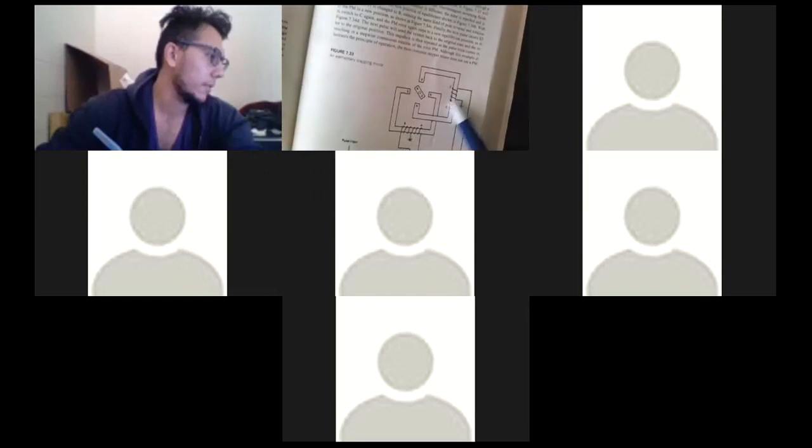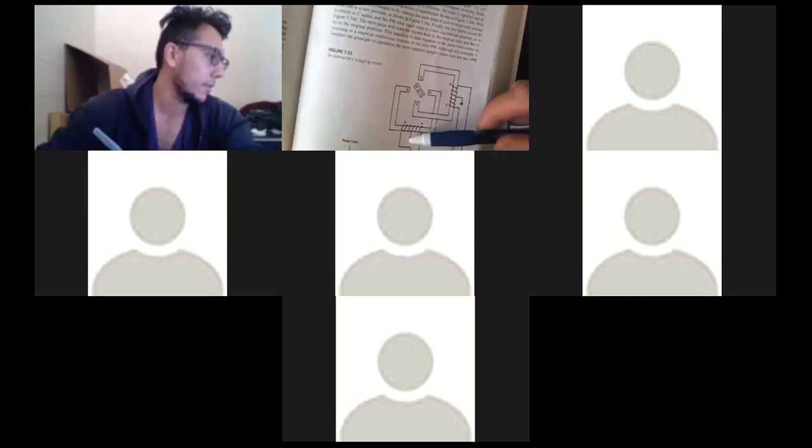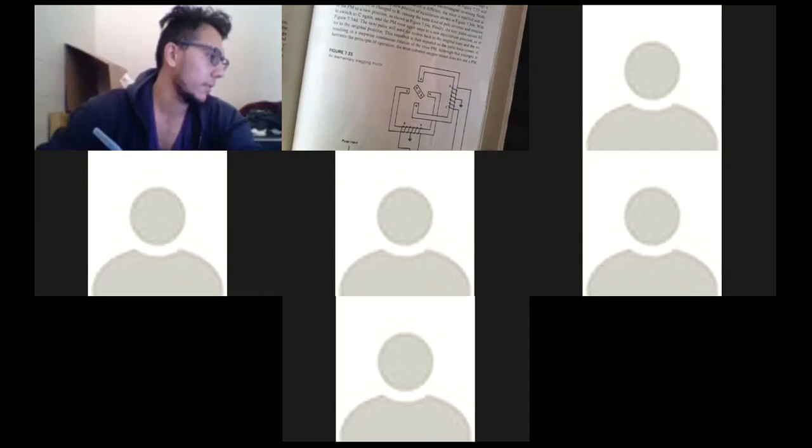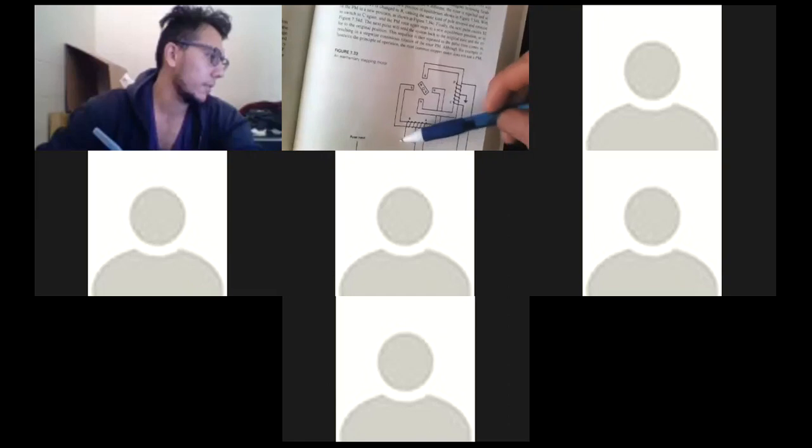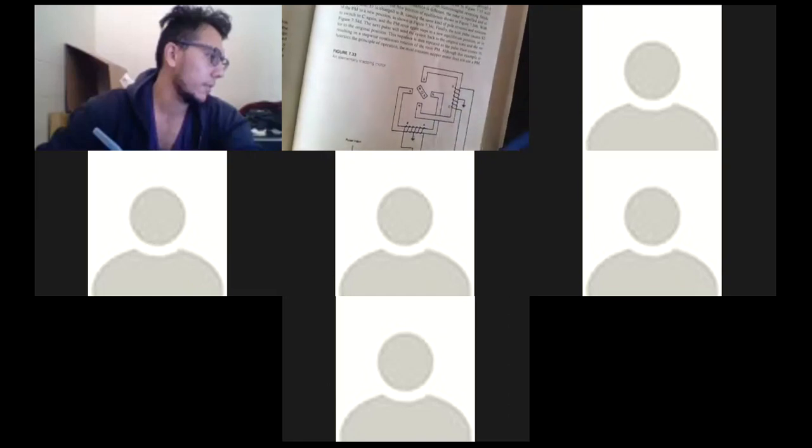So this is an example of a stepper motor. Generally, a stepper motor has 2 coils. That's all we need to know. We need to energize them. This one has 2 coils with a ground. Another stepper motor has 2 coils without ground. Some stepper motors have 5 wires, 1, 2, 3, 4, 5. Some stepper motors, called bipolar, have only 4 wires.